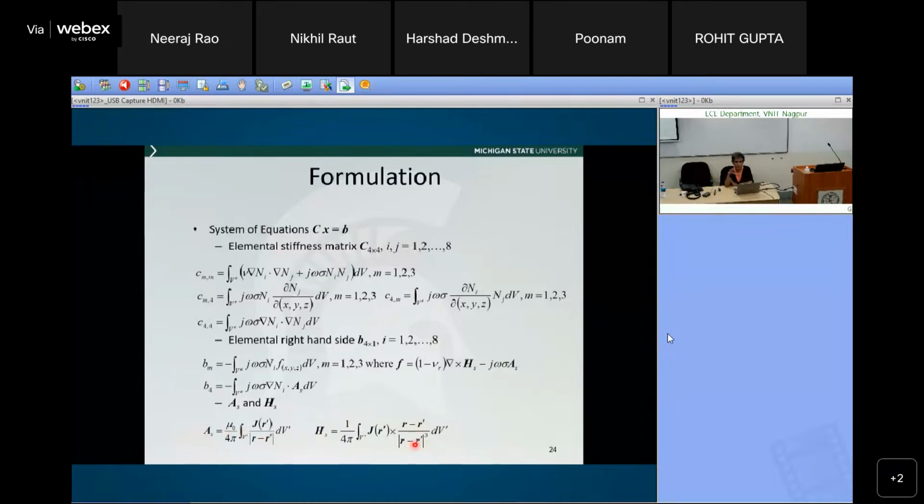So the benefit is basically I don't have to include the coil mesh at each position. That means the geometry, the source, the test geometry element, the matrix has not changed. Only the right hand side changes. So I just have to precondition it once. Otherwise, everything is repeated at every step.